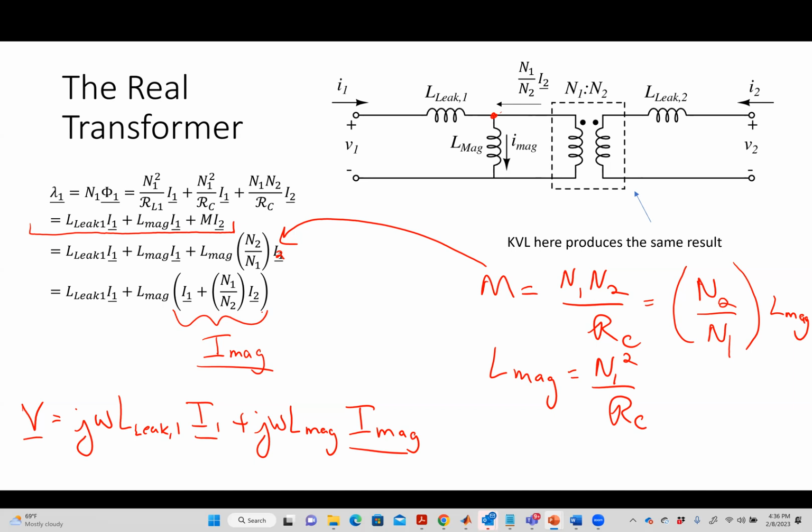Where did I place that loss? Right. So I said the core loss, we talked about that. You had problem 3 on the homework. Where did I put the core loss? There was a resistance in parallel with that magnetizing inductance. There was a resistance in parallel with the inductance coming from the core.